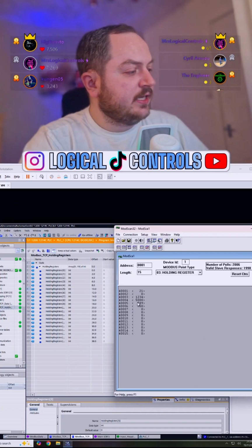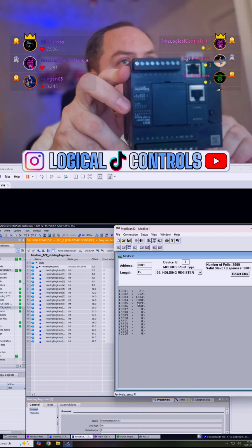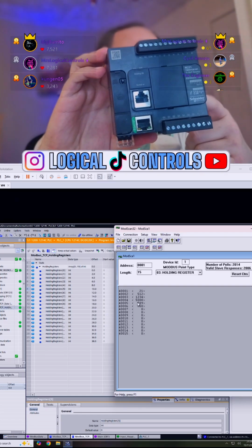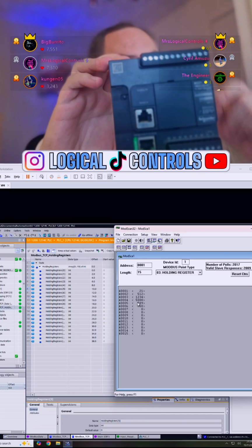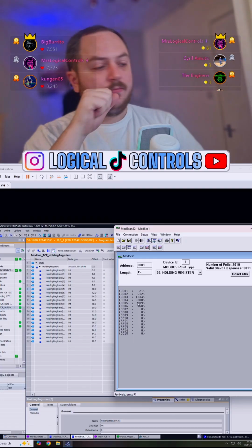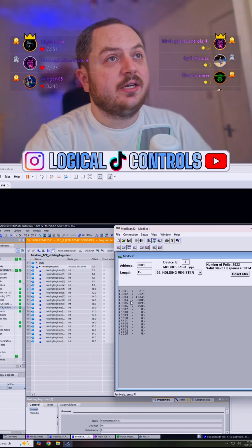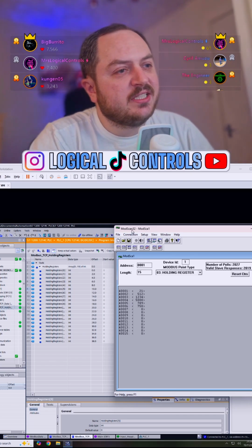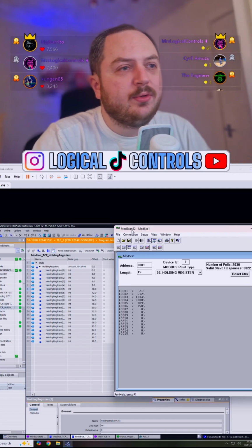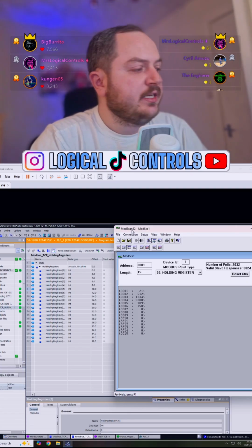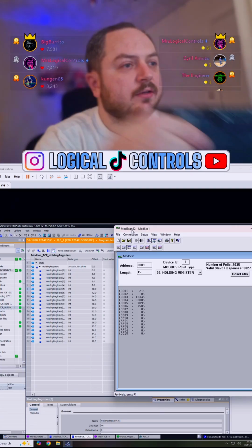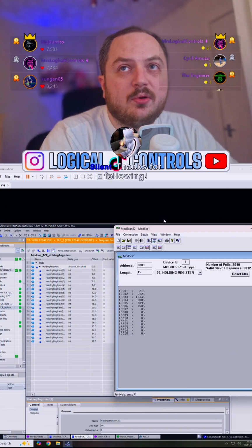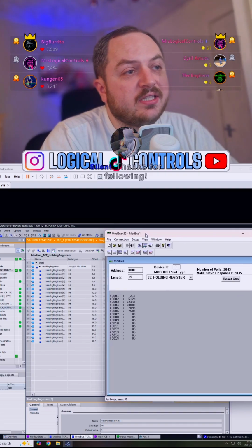And if I'd set up this Schneider PLC here, it's upside down, never mind, I could get this PLC to read data from that Schneider PLC. And you could use that Siemens PLC almost like a remote I/O, if it has a specific counter in it or something that's important, that you need to get into another device like another PLC. Modbus is a good way to do it. It's not the fastest protocol. It's quite an old protocol, but it's a very simple and straightforward protocol.